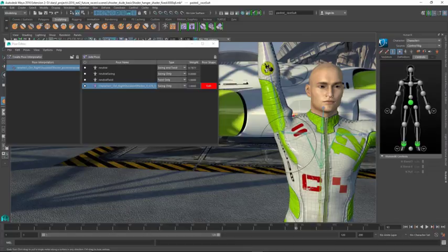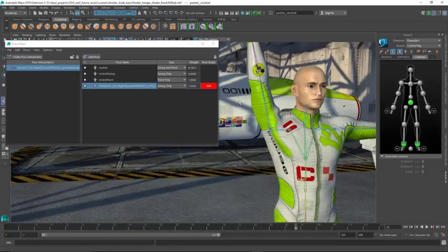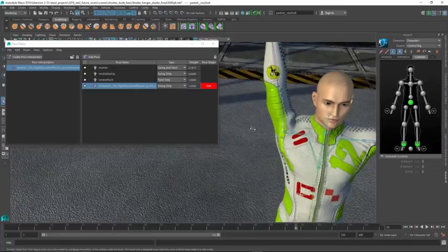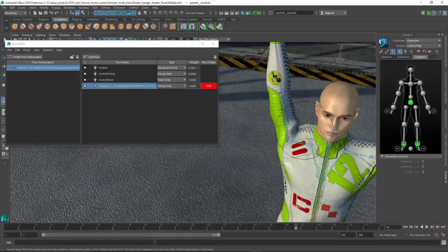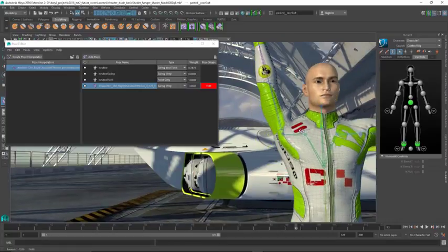So once I'm happy with that, I can go in here and use our new smooth target brush. I'm just going to use my smooth target brush to average that out a little bit, try to get that area to not distort quite as much. And I might go in here and just paint across the top of this a little bit and smooth out that target region right across there too. So that's looking pretty good.